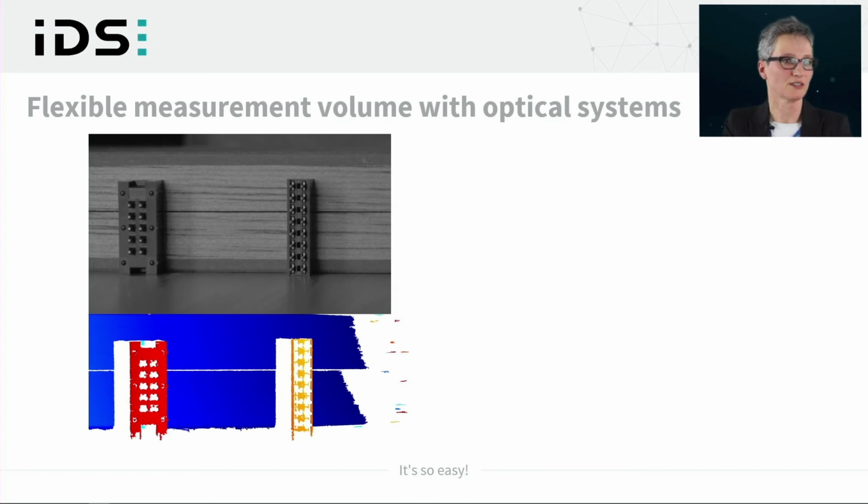And you see the red points are showing the connector, and the white squares inside are there because the pins are very small and reflective, and this is a challenging surface quality. If you have reflections on materials, they are likely to be not matched or wrongly matched, and thus you have data that is missing or that you cannot use.